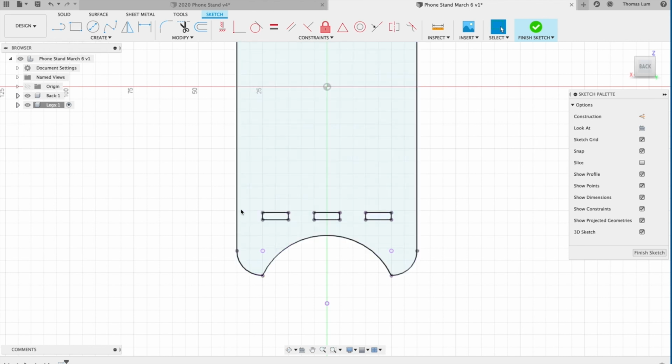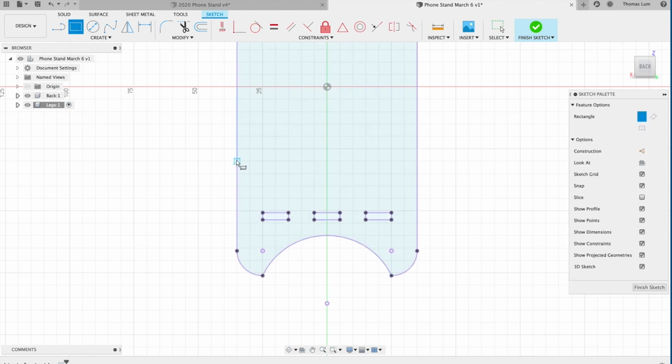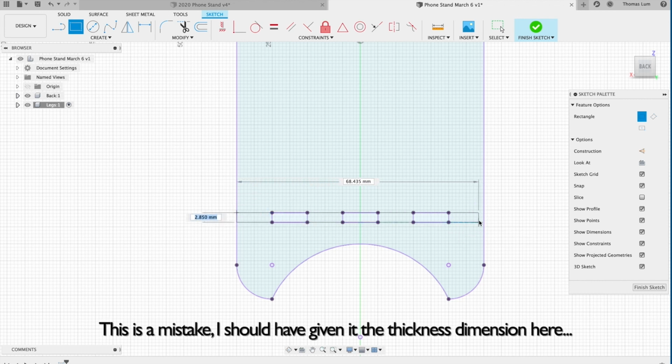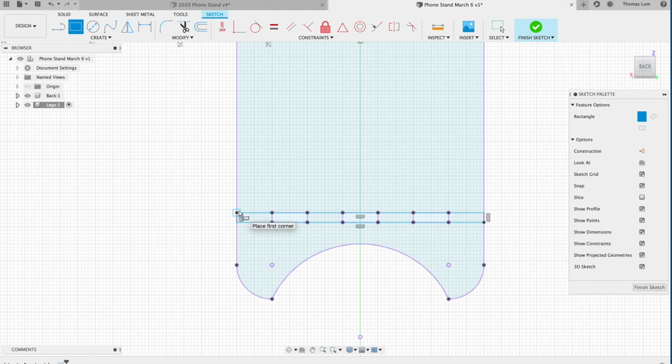All right. So what I'm going to do is build a rectangle right here, 2-point rectangle. I don't want it to snap on any of these grids here. What I want to do is say, hey, remember this. And as I pull this over, it'll actually remember where that was. And then I'm going to come down to this side, and then I'm going to snap to this piece, come over, and now it'll remember that. So it has a little bit of a memory. So if you hover over something for a second to pull it to the other side, it'll remember that part. All right. So that was all I wanted to do with that sketch.